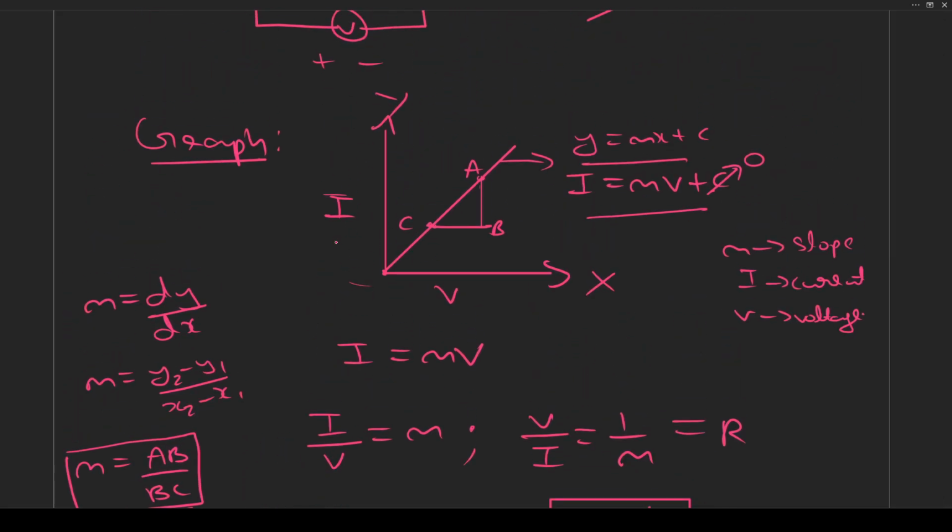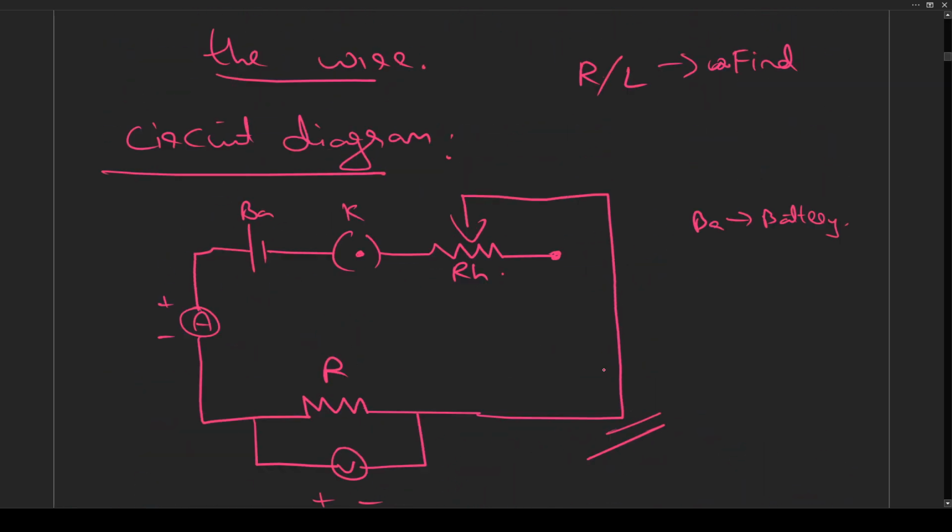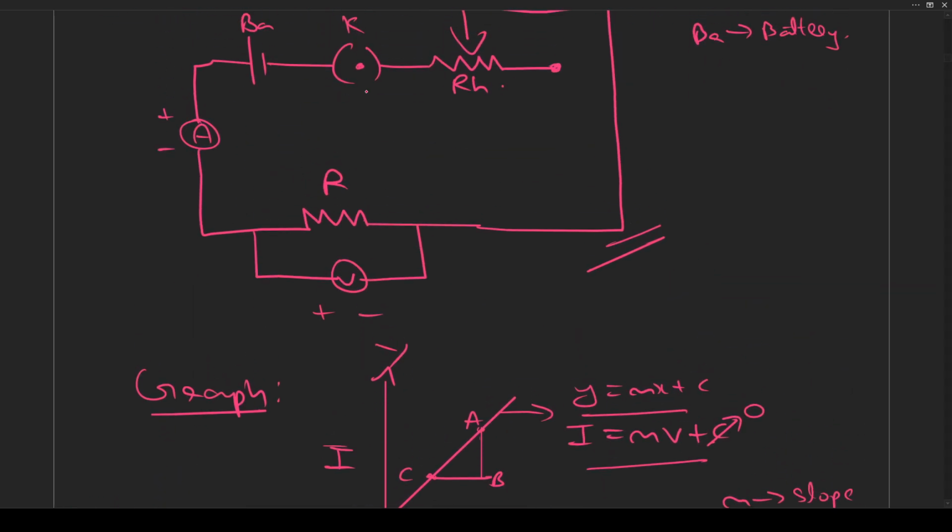Resistance, we take a graph of IV values. How we should find this IV graph? In our previous experiment, I showed how we should adjust the rheostat values. If we adjust one value, for example, after we start the battery or close the switch or plug key, let's assume the ammeter shows 1 ampere, then the corresponding value in the voltmeter shows some 1 volt. These both are noted down.